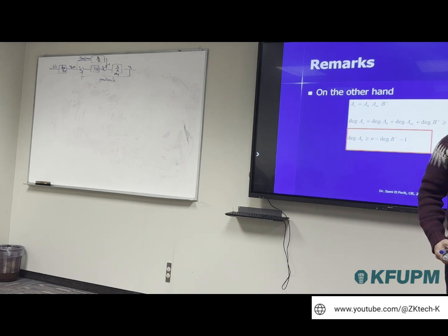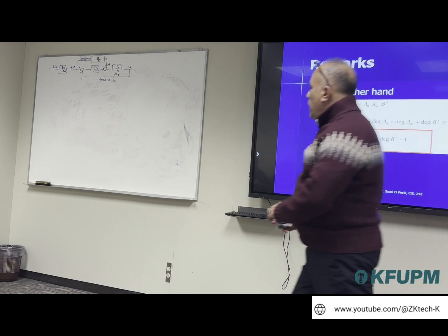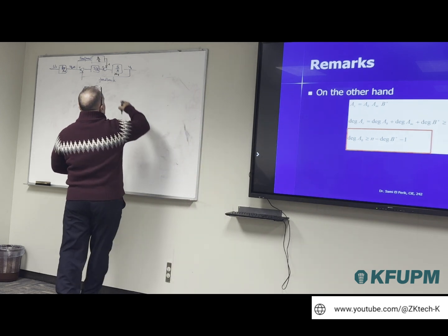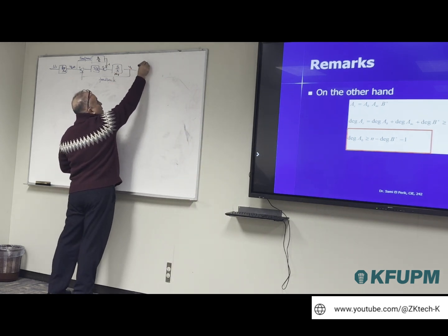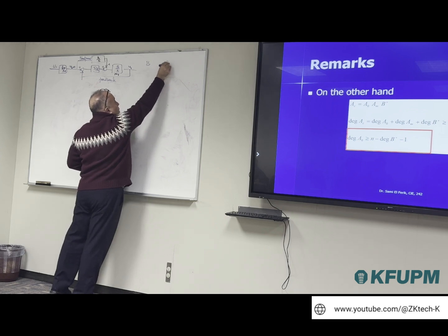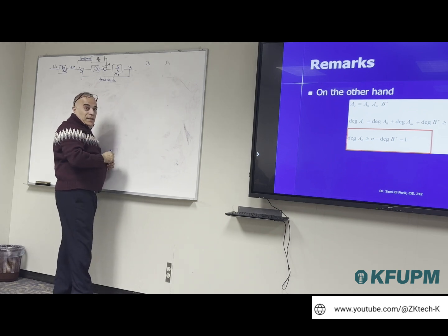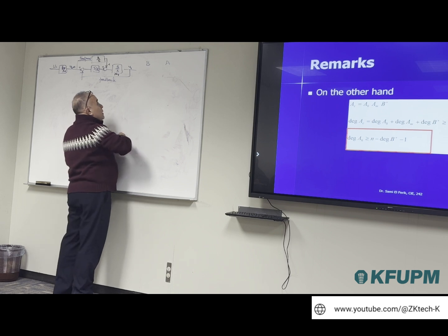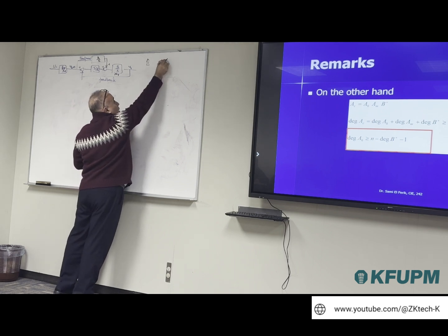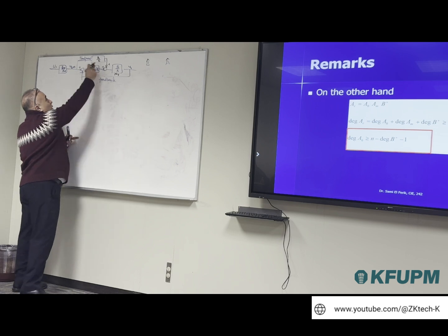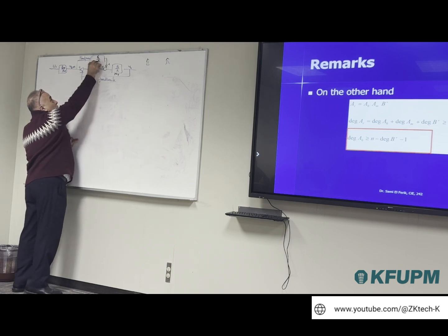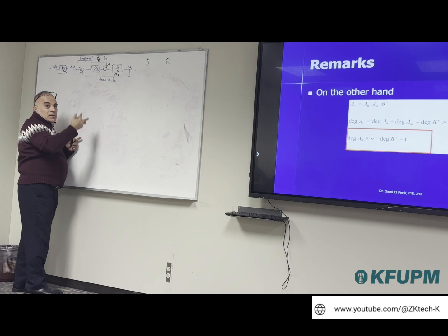There is a small. Sir, I have one confusion here. Our model is B upon A. Yes. But our estimated model is the inverse of A over B. When we estimate the model, in this model there are two terms. Yes. There is the B and there is the A. So what we estimate is also B and A. Yes. So what we get is B hat and A hat. Yes. But when we implement it in the controller, we put the A hat over B hat. They are two polynomials. They are inverse.